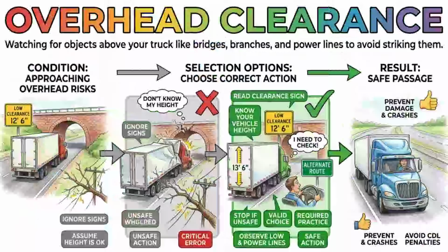Sometimes a hazard appears so suddenly that you do not have enough distance to stop, forcing you to steer around it. Evasive steering requires a firm grip on the wheel and a smooth, quick movement to change direction. You should avoid braking while making an aggressive steering maneuver because locked wheels will not turn, causing you to plow straight into the hazard. It is also important to know that steering onto the right shoulder is usually safer than steering into the left lane, where you might collide head-on with oncoming traffic.